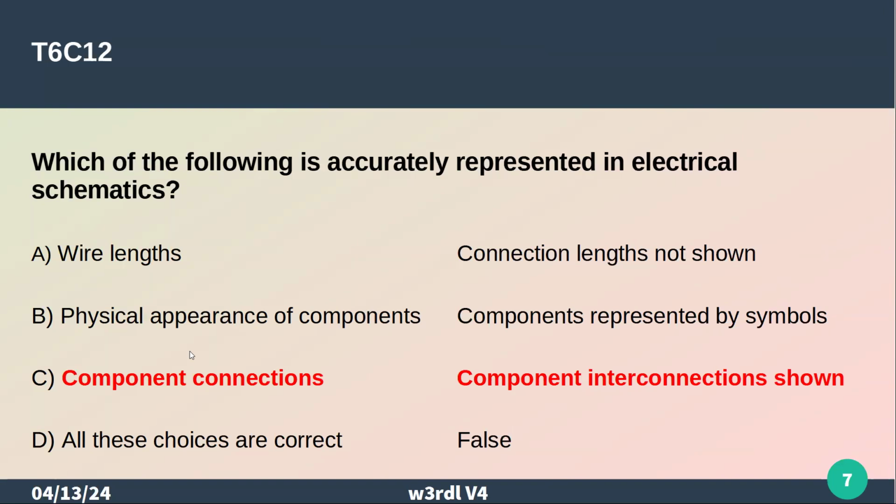Remember that the layout of the circuit board and the layout of the schematic are for two different purposes. The layout of the schematic is to aid in troubleshooting. So the technician needs to be able to look at it, interpret it, and follow it through. But when you go to the circuit card, the rule is real estate. You want to pack the components that you need into the smallest possible package, because you don't want to have a truck to haul around your radio.